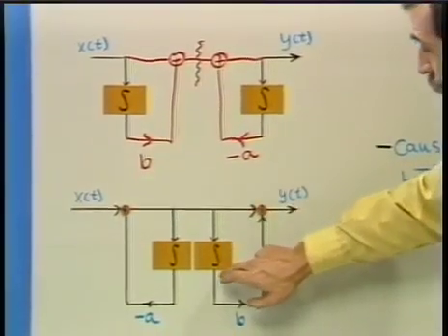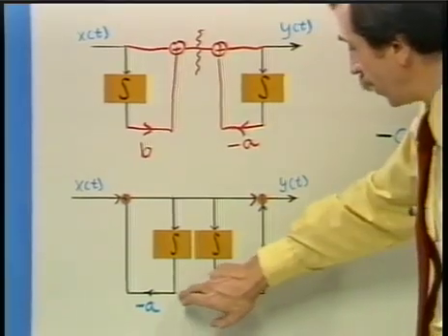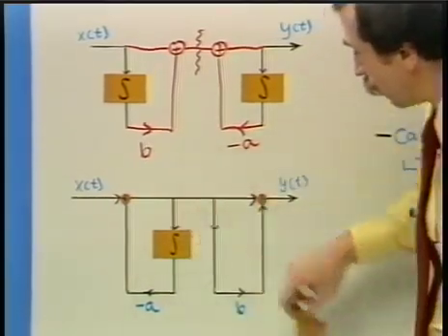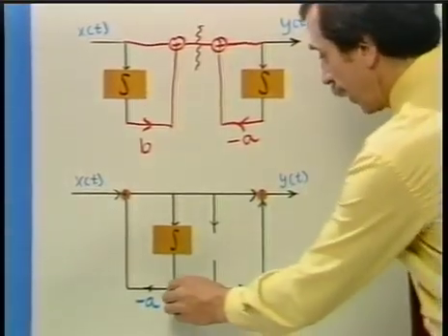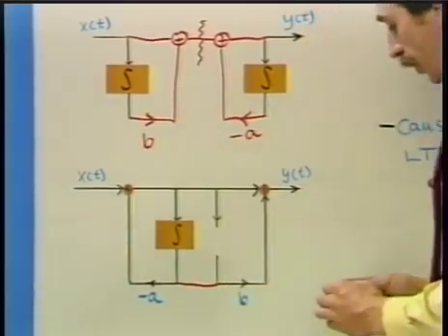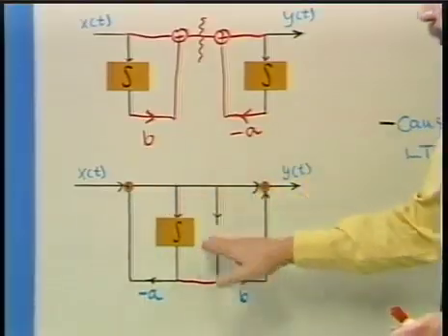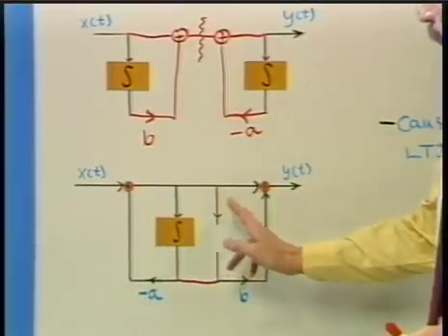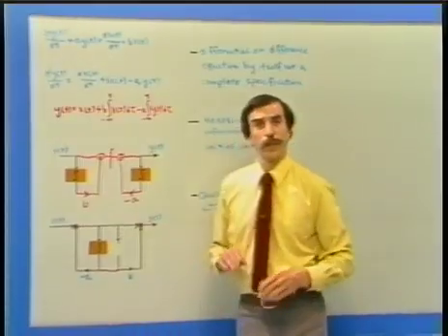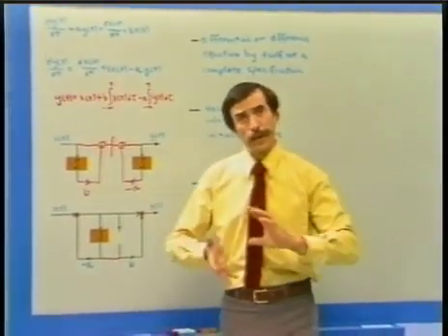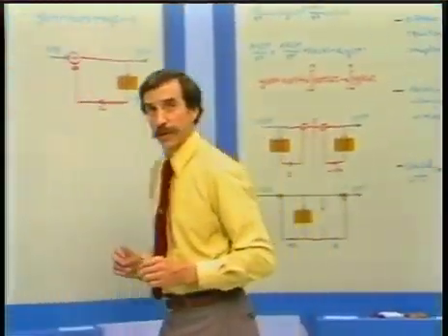So in fact, rather than using this one, we can simply tap off from here. We can remove this integrator, break this connection, and tap in at this point. And so what we've done, by interchanging the order in which the systems are cascaded, is reduce the implementation to the implementation with a single integrator, very much similar to what we talked about in the case of the difference equation.